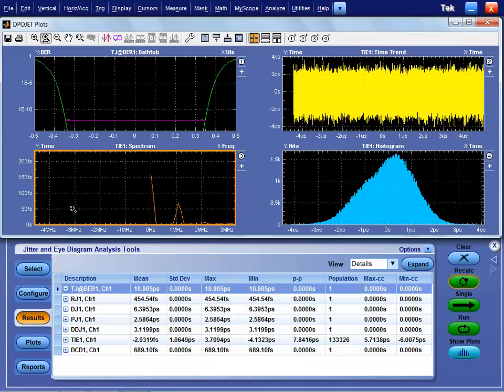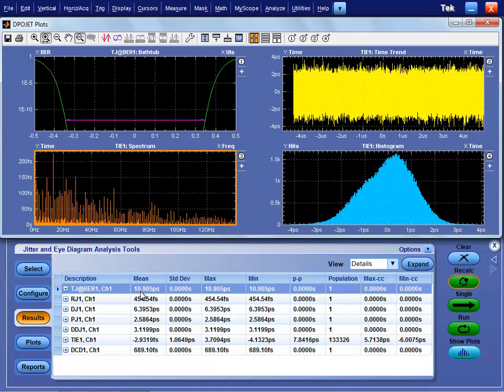And that 1 megahertz is now there, but it's been suppressed by that clock recovery all the way down to 50 femtoseconds. So by turning on an appropriate clock recovery, my numbers came in line. Now in my system, if I knew what that 1 megahertz was, that's good. I can go figure that out and clean it up. But in reality, the receivers are probably going to track and discard those low frequency contents anyway. Depends on what you're trying to do, if you're trying to be compliant or debug. And this tool set is flexible enough to give us all those.